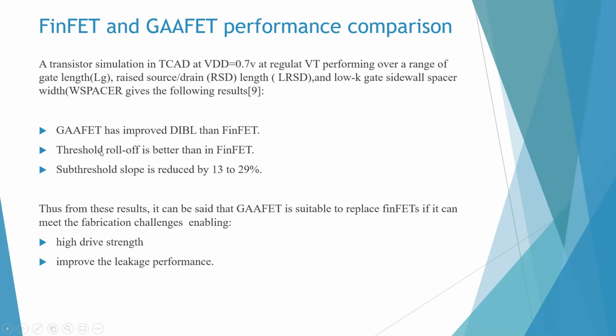Also, they have reduced threshold voltage roll-off, and reduce the subthreshold slope by 13 to 29%, which is a very great improvement. Thus, from these results, it can be said that gate-all-around FETs are suitable to replace FinFETs only if they can meet the fabrication challenges.